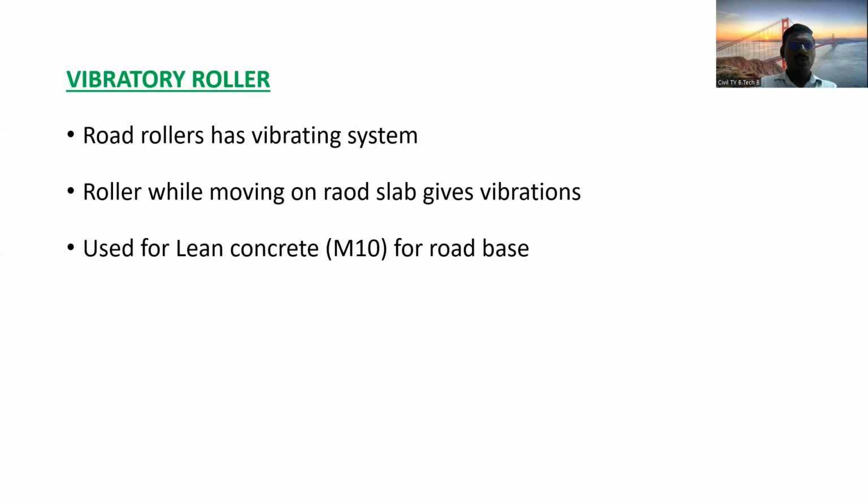Then vibratory rollers are also available. By using a vibratory roller, we can compact the concrete also. The vibratory rollers have a vibrating system. Have you seen on the road, there are vibratory rollers we can use for the compaction of soil also. The weight of the roller is also there for compaction, but they are vibrating also. Due to the vibrations, the air voids or air content from the soil get removed.